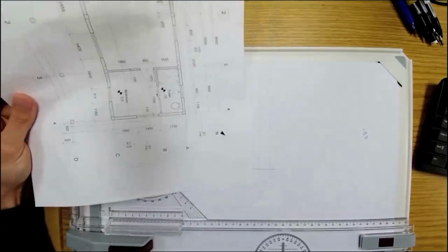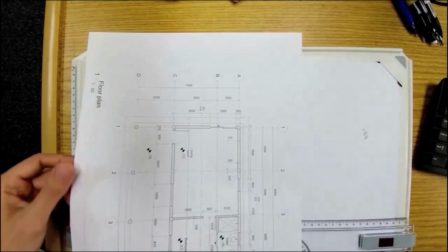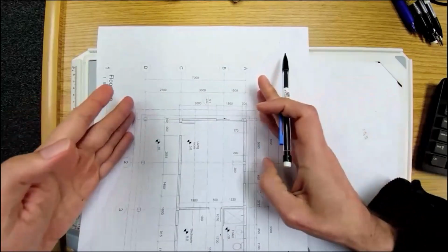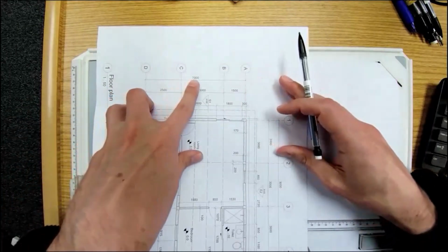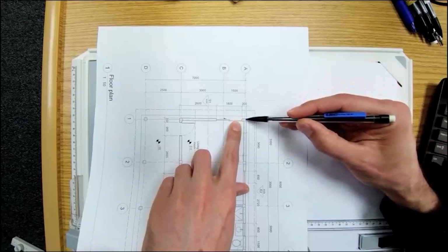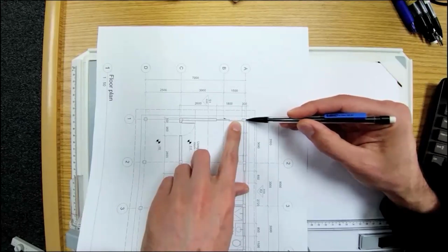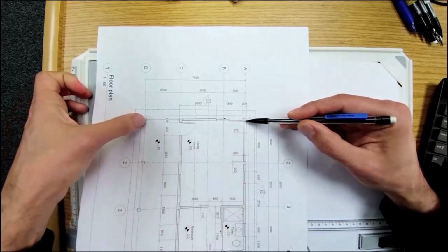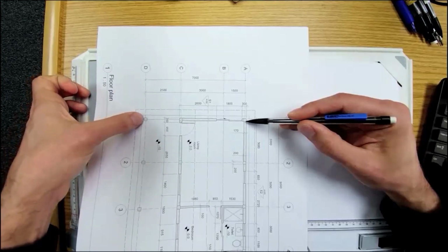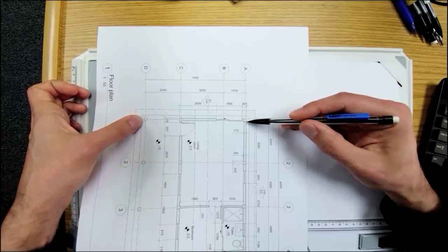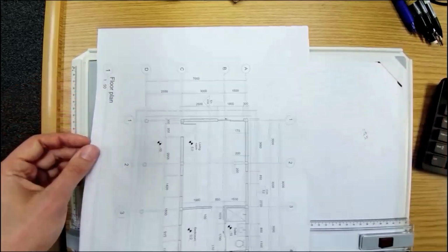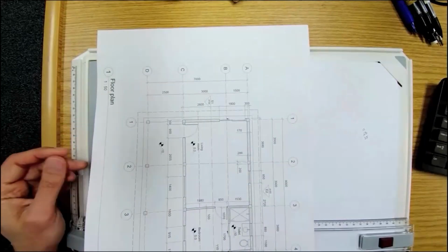We can see from our floor plan that the total size of this house is 7,000 plus 100 here for half the column, and plus 100 here to the left to account for half this column. So that's 7,200 millimeters, divided by 2,